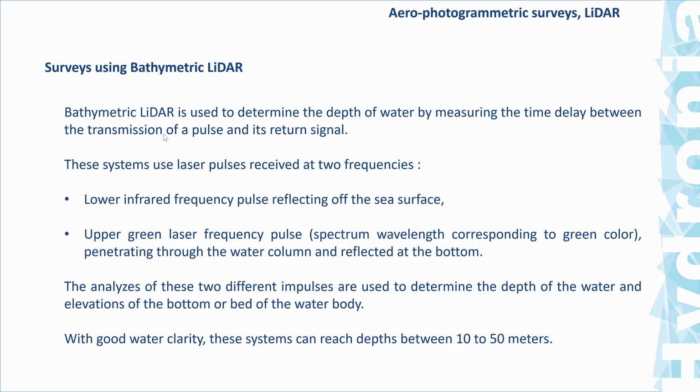Now you have nowadays bathymetric LiDAR that is used to determine the depth of water by measuring the time delay between the transmission of a pulse and its return signal. So it actually penetrates the water. And this allows an approximation of the bathymetry or the topography of the riverbed underwater. So these are relatively new systems that are being employed more and more, but you have to be aware that if your source is a standard LiDAR, it will not determine the bed surface, but only the water surface elevation. That may be an issue that we will come back to.